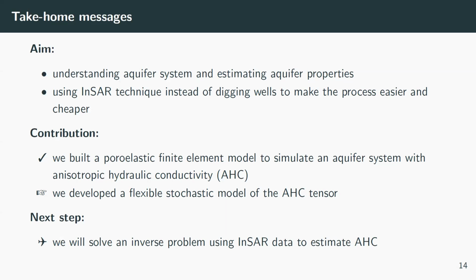So we built a poroelastic finite element model to simulate the aquifer system with AHC. And then we developed a flexible stochastic model of the AHC tensor that I explained today. And the next step would be to solve the inverse problem using InSAR data and estimate the AHC.